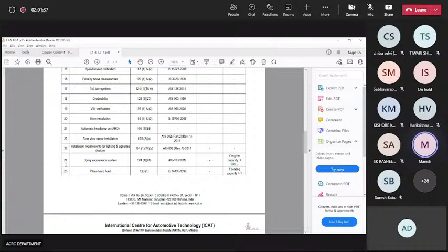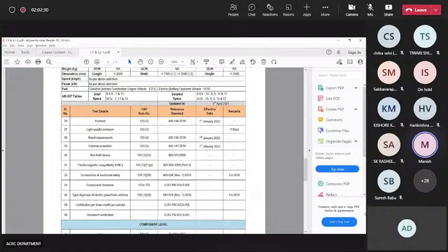Yeah. Now again comes the footrest test. Whatever footrest you have in a vehicle also comes under loading. There is a certain load defined, 170 kg is put on the footrest. In a scooter case, the front footrest and the rear pillion footrest both have to be loaded, and they should withstand that particular load. So again, AIS 148 defines that particular load case. And the remaining is the lightweight container. If it is like a pizza box and all those things fitted on the vehicle, that comes under that category. But we are not going to get into that detail.